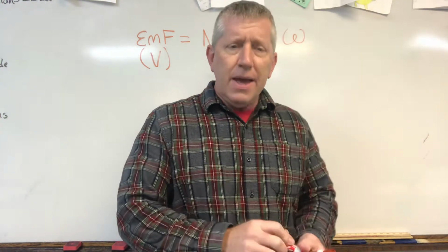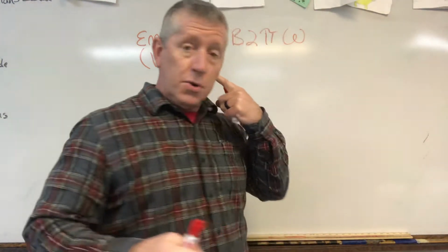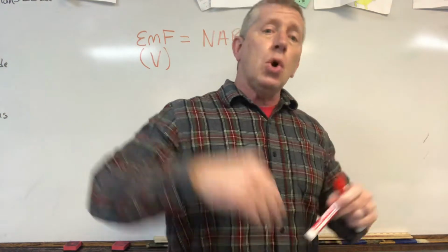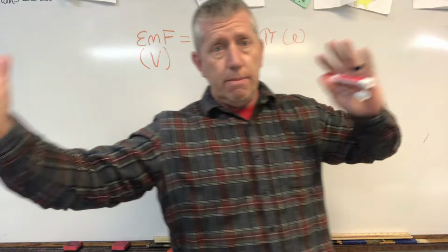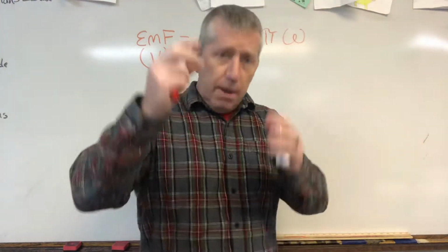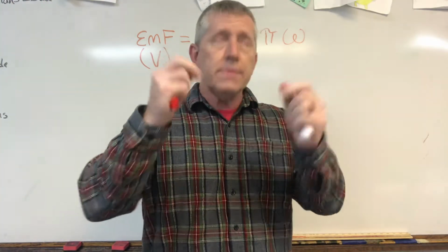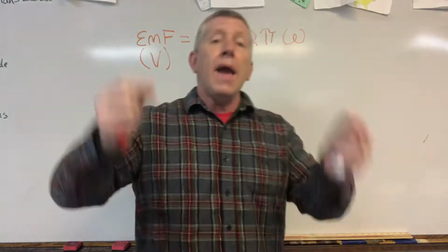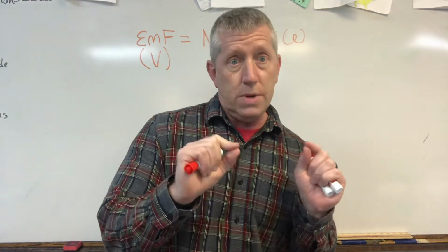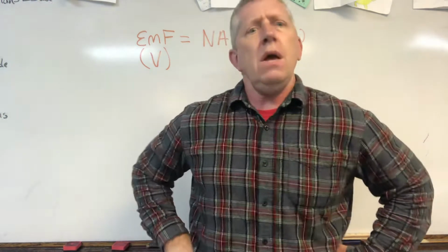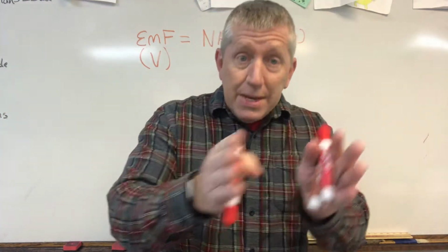Now, how do you get 250,000 volts down to 120? Well, first you get it to 10,000. Once those big lines that are traveling for miles carrying that electricity reach what are called transfer stations, they take the 250,000 volts and step it down. Step it on down. We'll talk about stepping up, not that kind of stepping up, but we're stepping it down to 10,000 volts.